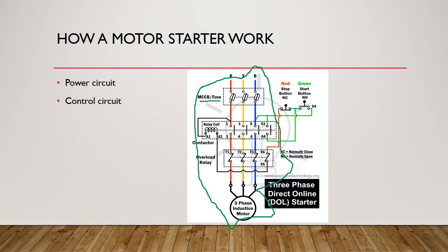Then that connection goes to the contactor. The contactor is connected together with an overload relay, and that goes direct to a three-phase induction motor. This is for the direct online, the DOL starters. So that connection all the way is what we refer to as a power circuit.